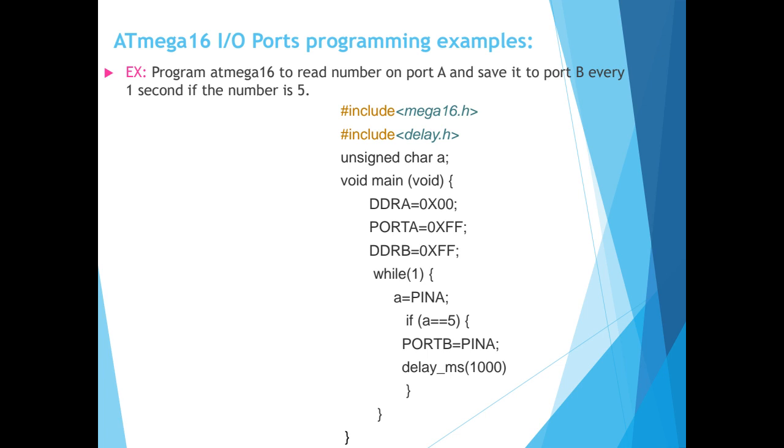logic 1. Why did you forget the previous sessions' discussion? Listen to me: for configuring a port as input or output, we use the DDR register, okay?